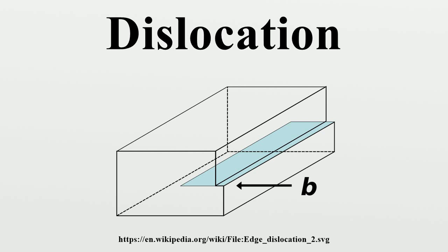Dislocation climb. Dislocations can slip in planes containing both the dislocation line and the Burgers vector. For a screw dislocation, the dislocation line and the Burgers vector are parallel, so the dislocation may slip in any plane containing the dislocation. For an edge dislocation, the dislocation and the Burgers vector are perpendicular, so there is only one plane in which the dislocation can slip.